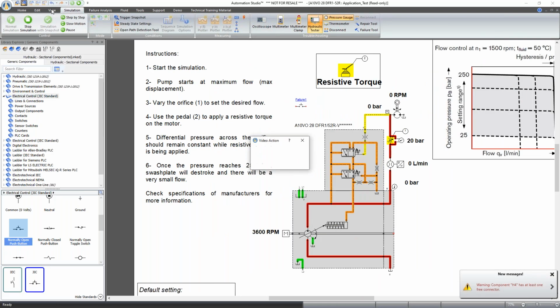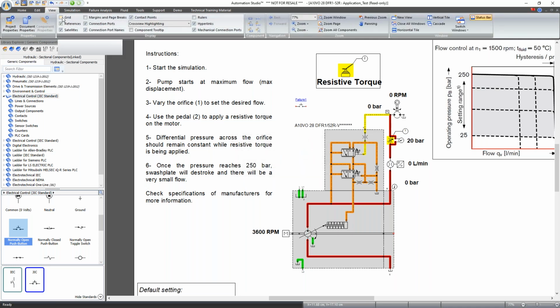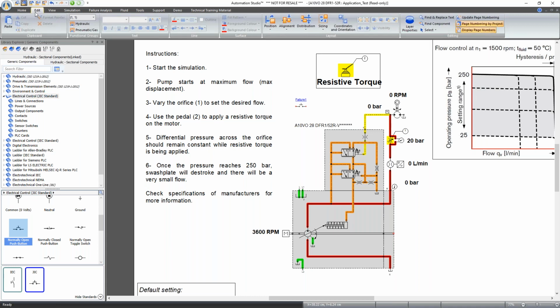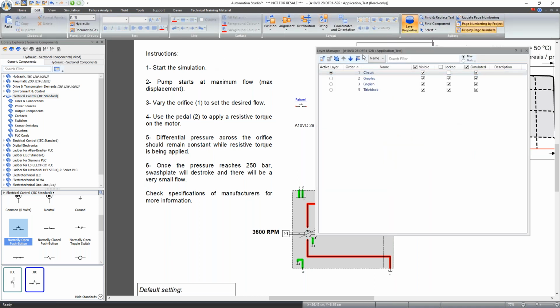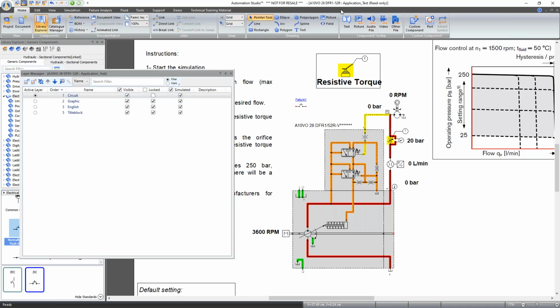So everything else that you can do when you are not in simulation mode, or almost everything, sorry, showing the grid, showing the satellites of the component, the port name, everything, managing the windows and so on. In edition mode, you will show the layers, make some portion of the schematic visible or not. All of these objects will be available. You will not be able to edit.